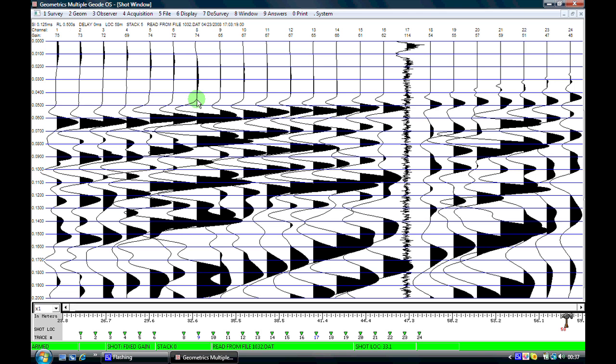It's important with seismic refraction that you do examine the data closely in the field, because it's absolutely critical that you're able to identify where these first arrival points are, or first breaks if you like, because quite often what looks like good data when you're in the field, when you come back to the office to try and edit the data and process it to interpret it, these first arrivals may not seem very sharp, but by then it's too late. At the moment, if I wish to increase the amplitude of these and therefore process the data with a greater accuracy, I can stack more times with the sledgehammer, which will increase my signal to noise ratio and make these first arrivals sharper.